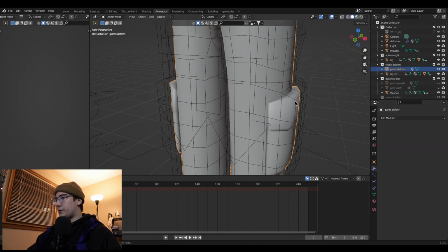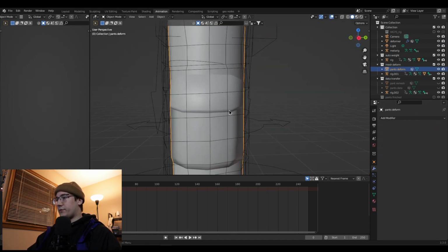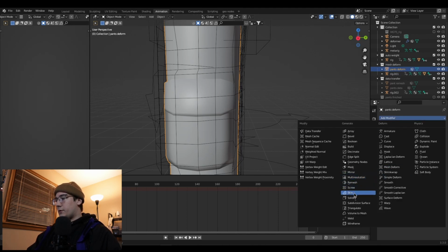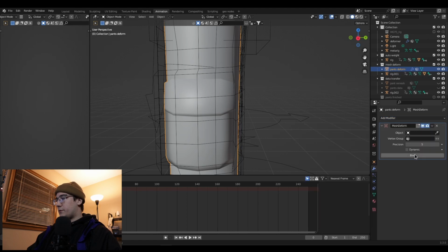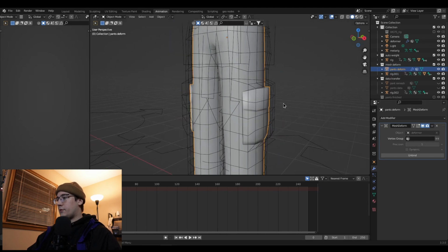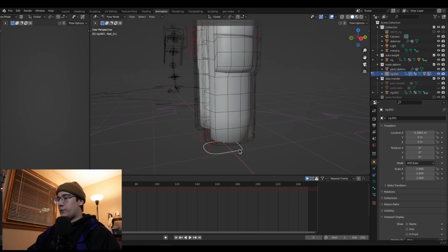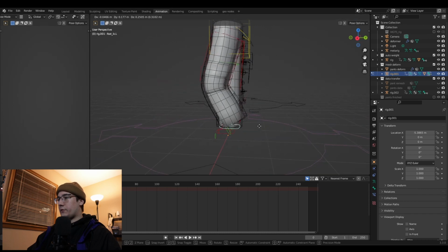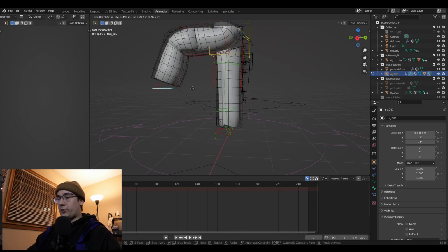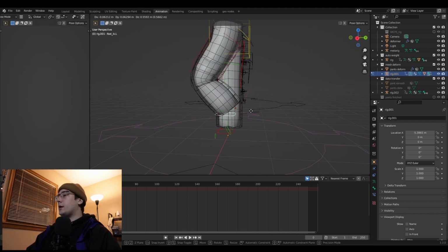And then we're going to go back, we'll go into wireframe, actually here, display as wire again. And we want to take this modifier off because it's going to try and tug at the deform again. And we're going to try and reapply this modifier. Mesh deform, object, deformer, and hit bind. Now everything is bound, and let's see how this works. And it's perfect. So again, very important that everything stays within the bounds of the cage mesh. Otherwise, it just doesn't bind and it doesn't work.